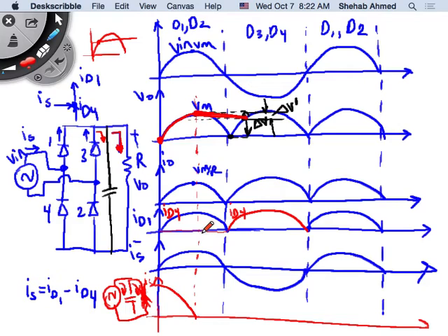Now I have a resistor. Okay, if I put the resistor in there, and then after that, what's going to happen? Sorry, assuming still no resistor, this would be my supply current. It has charged my capacitor to Vmax. The capacitor voltage will be maintained at Vmax because it's an ideal capacitor, right? No resistance at all. It will be maintained at Vmax. It will never go down. If it never goes down, then the supply will never conduct again.